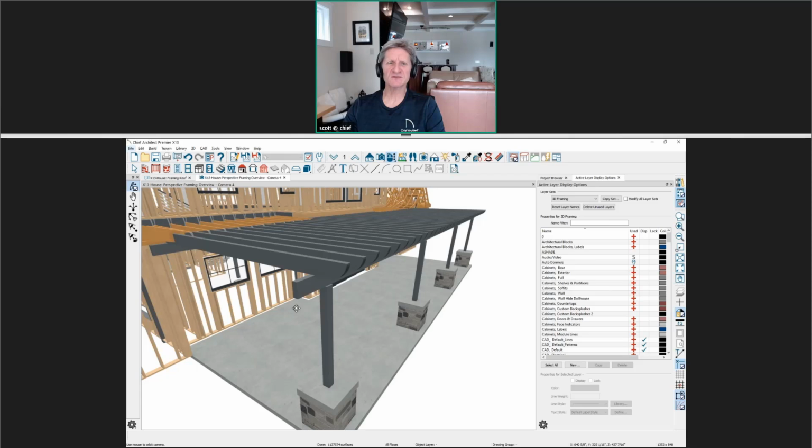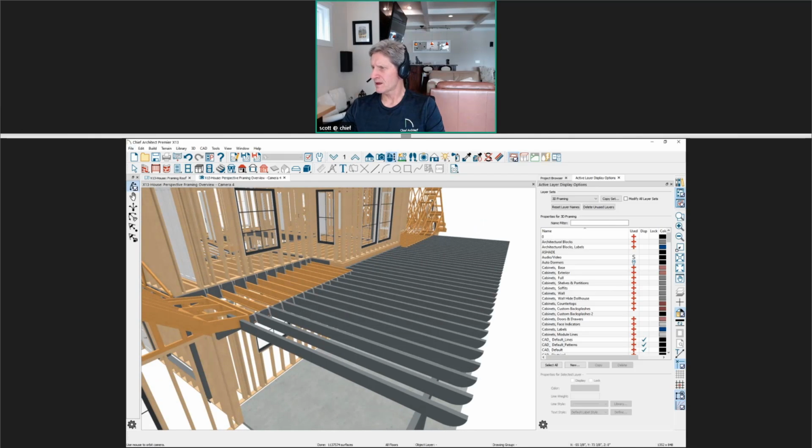That is new, but when you expose your rafter tails, if you want that member to change where it's exposed from the eave out and you've removed your soffit, I can't change the framing member depth. What I can do is build my own rafter profile that would go from a 2x12 maybe to, I'm just looking to see if I have one here.